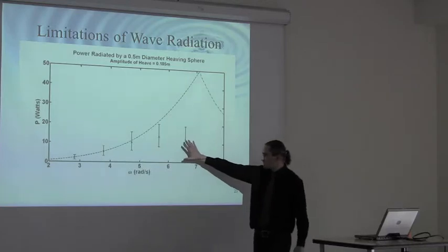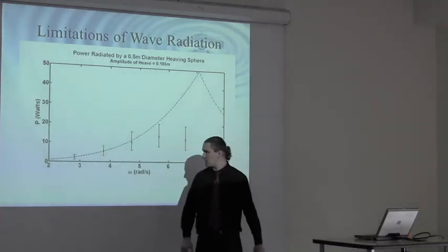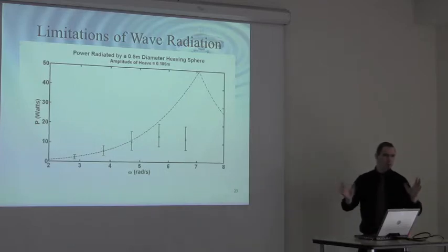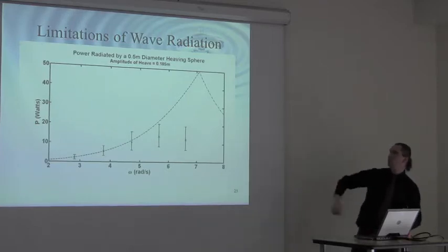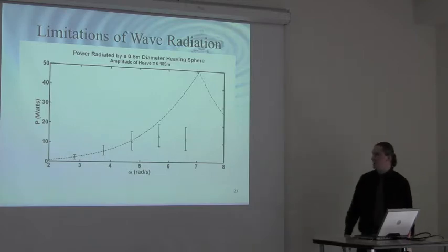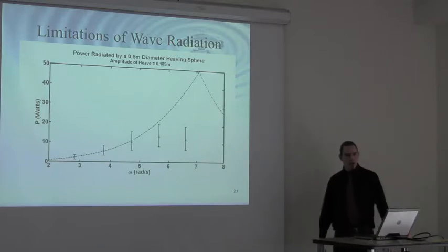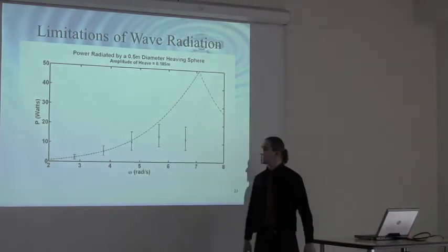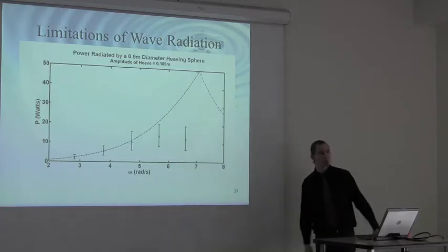The interesting thing about the power curve is I've plotted here the heaving sphere. So I've taken the sphere's dimensions, calculated my characteristic cylinder, and then calculated the displaced volume and the wave breaking limit based on those 2 factors. And down at the low end of motion, the sphere matches pretty well.